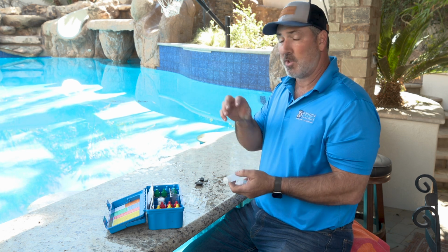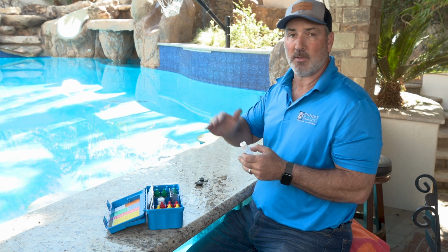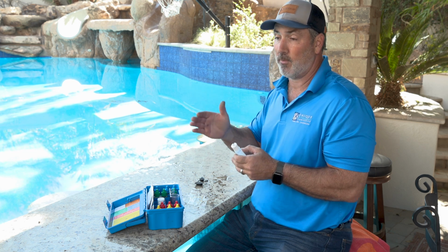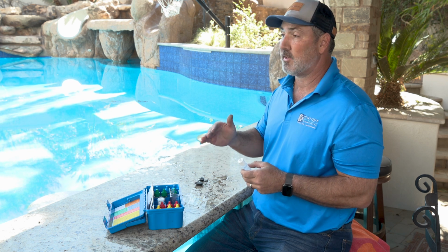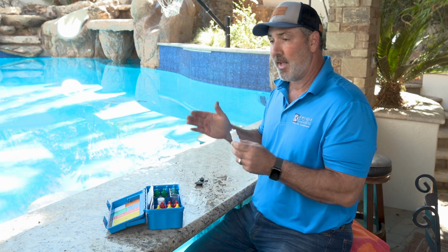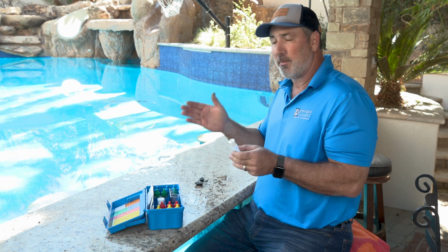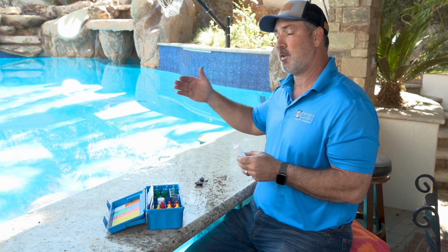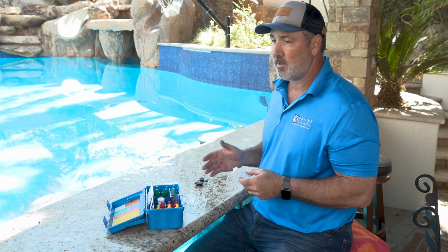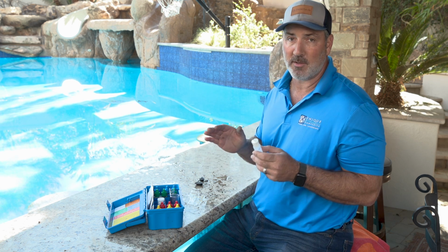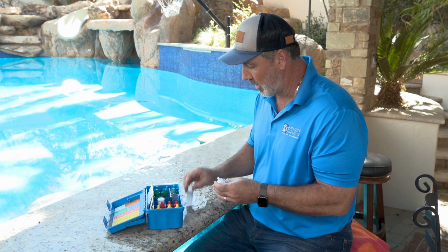And then you'll see that as you add the stabilized chlorine tabs, like the tab feeder, that cyanuric level starts to go up, maybe 10 points a month or so. So after 10, 11, 12 months, you can have cyanuric levels up to 170, 180, and that's not good. So I would say keep your cyanuric between 50 parts per million, maybe up to 100 at the most, and then as you start to get above that, you want to start thinking about draining your water. Water drains are probably more common and more necessary because of high cyanuric acid levels, not because of high calcium levels. So just keep that in mind.